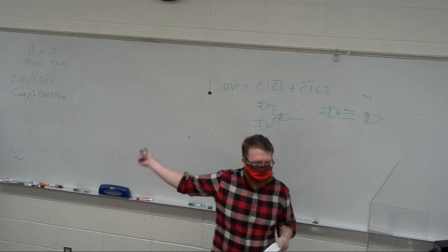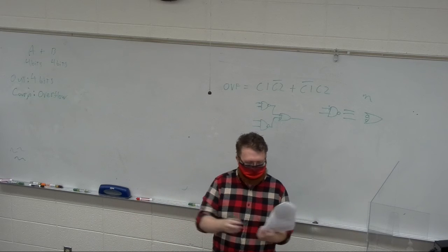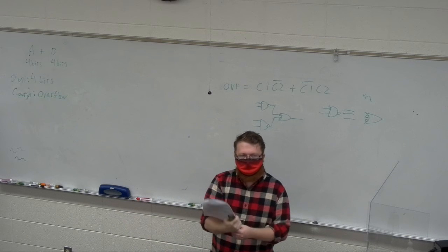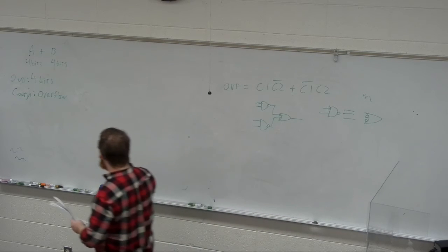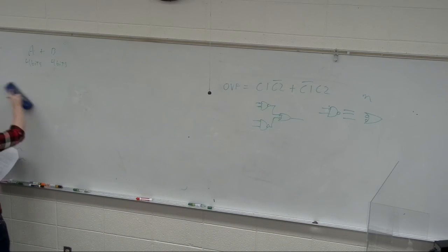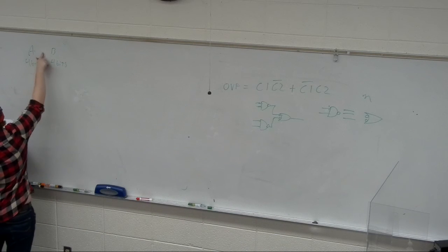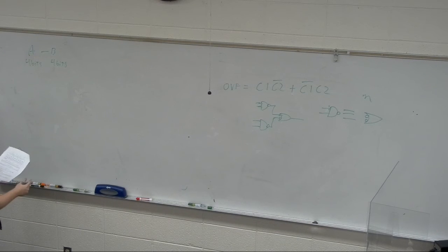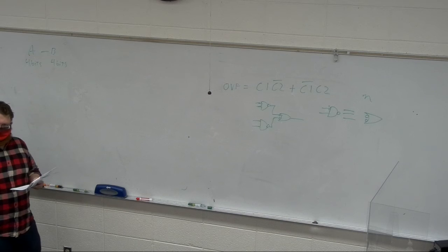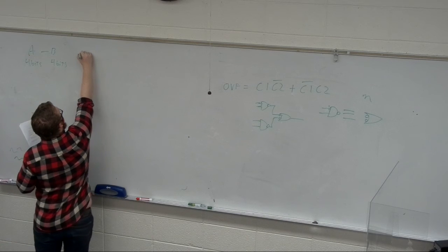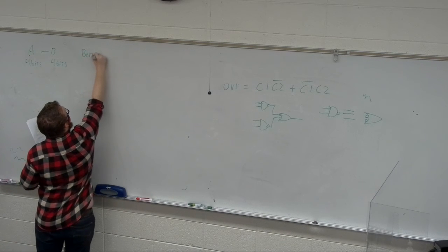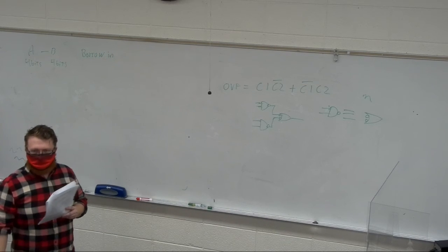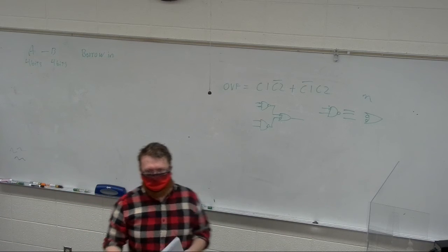Anyways, the point is what we did was just an algorithm. You'll do lots of algorithms. We're gonna stick to simple ones for now. And in this case, our next algorithm is a 4-bit full subtractor. We're going to stick with A and B, and we're going to do A minus B. But the thing that we're going to change is instead of a carry out and carry in, we're going to start worrying about a borrow in. So we have the idea of borrowing in our subtraction, right?